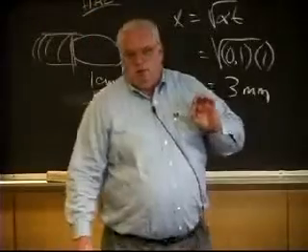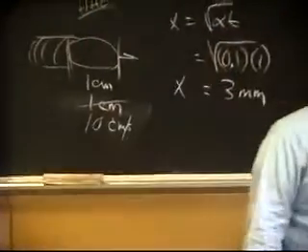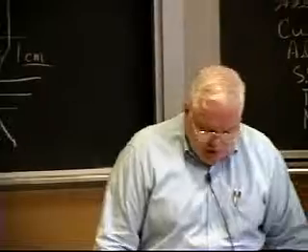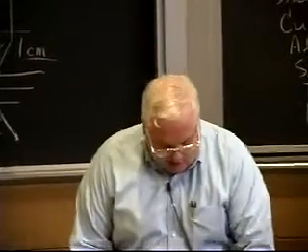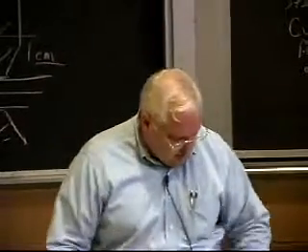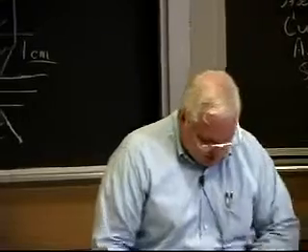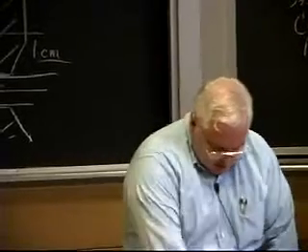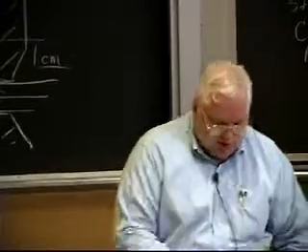So in principle, in a laser weld, I might be able to narrow the heat affected zone down to 1/10 of its original size. However, not a tenth, but a third of its original size. If I go 10 times as fast, a simple heat flow analysis would say that I'll get 1/3 the heat affected zone size. However, that's not always true.